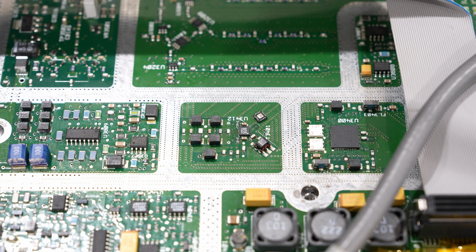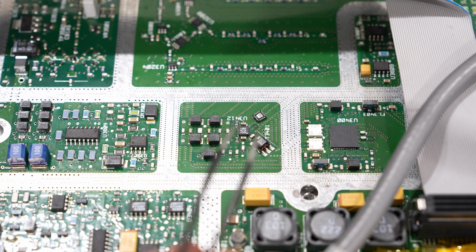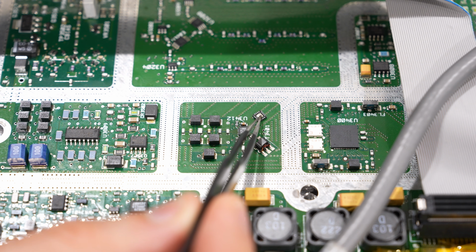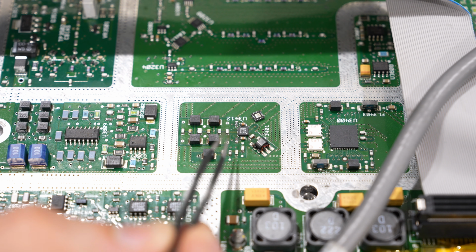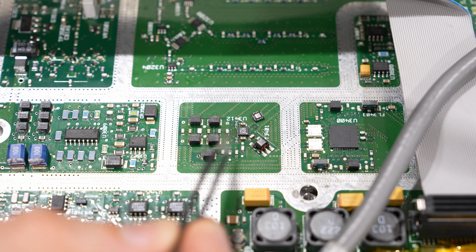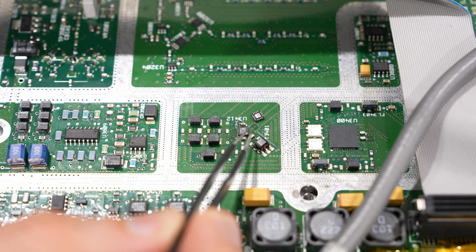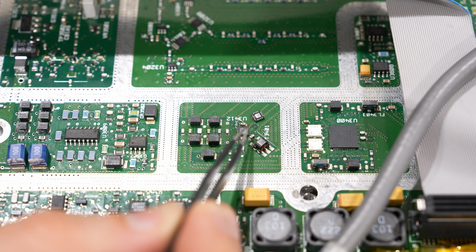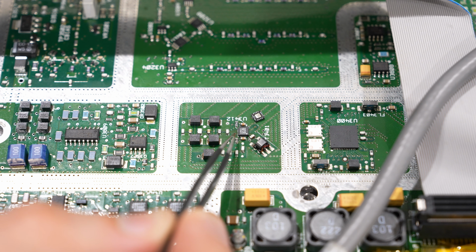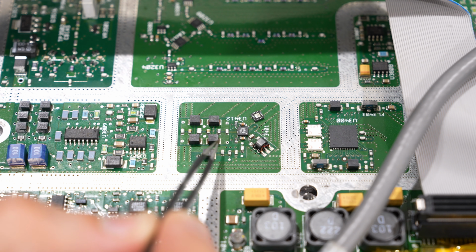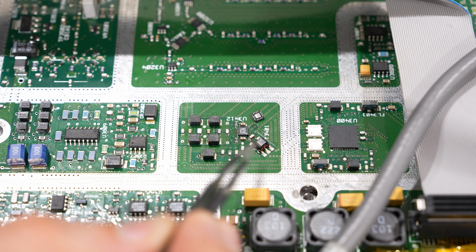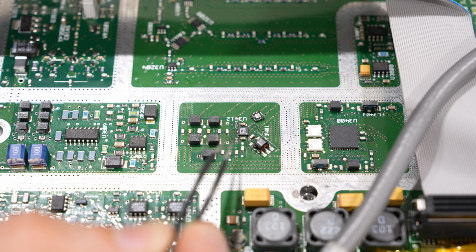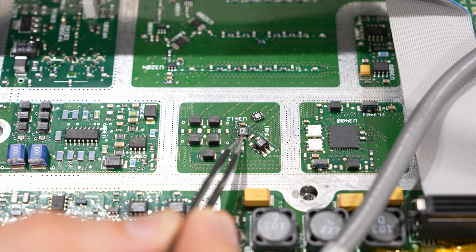And through the magic of 4K television, here's the replacement. It did take a long time to do this. As you can see, the parts do have a ground at the bottom and a lot of heat was required. This is a big board with many layers, a lot of ground in order to remove that. And even after I did, one of the pads came off with it, and luckily it was a pad that's not being used. It's not exactly centered, but visually I think everything is soldered correctly. All these components had to be redone around it. Some of them may be a bit crooked. I was worried about this transformer, as the heat applied to it can destroy the enamel and short it out. I did cover it as much with tape as possible, but you can see things are really close to each other. But yeah, this is the old one, and this is the new one.